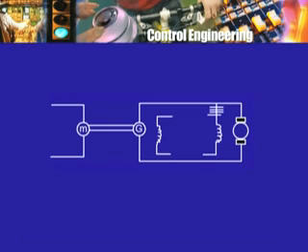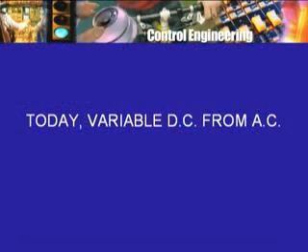So this just indicates that solutions are possible of various kinds, although today one would probably not use this solution for the simple reason that we have rectifiers available whose efficiency is very high, and therefore a desired DC voltage can be produced from a fixed AC voltage supply, that is a variable DC voltage can be produced from a fixed RMS value AC supply, and therefore you can drive a DC motor, separately excited DC motor, at various desired speeds.